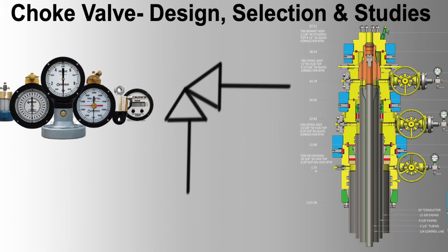Design considerations: ensure the valve can handle the maximum expected pressure differential. Select materials that can withstand potential corrosion from produced fluids. Operational concerns: monitor for liquid slugs and gas blow-by that can affect downstream equipment. Implement safety measures to handle sudden pressure spikes. Maintenance: inspect the valve for wear and tear, particularly in high-pressure drop applications. Schedule maintenance during planned shutdowns to minimize impact on production.